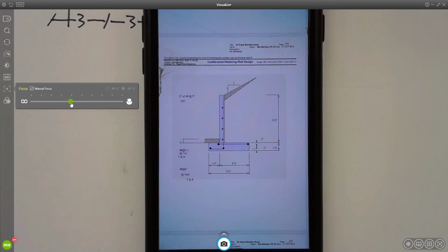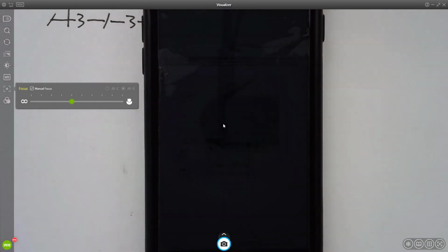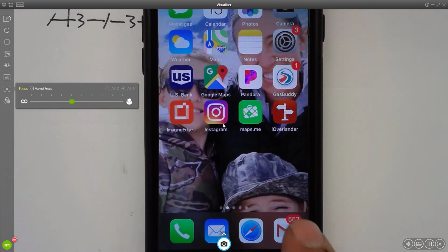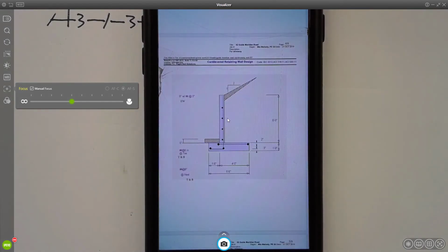Focus. Okay. So this is a retaining wall design I was having done for some people that are building a shop. So there's a big footing that goes in the ground, and then this is a concrete wall that goes up, and you can see there's a slope of soil behind it, right? So there's a shop floor here, and then they're digging this kind of foundation into a hill. And so there's a slope that comes down. So this is acting like a giant cantilevered beam, right?